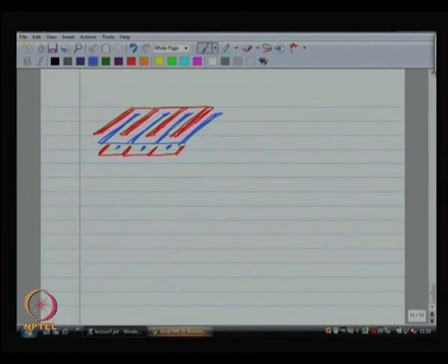So, I am not sure if it is clear, but on the higher layer, this is metal x plus 1 and this is metal x. Okay. On metal x plus 1 you do this fingered capacitor, and on metal x right beneath that you do the exact opposite. So, now not only do you get the side walls for your capacitors, you also get the surface area of the capacitor.